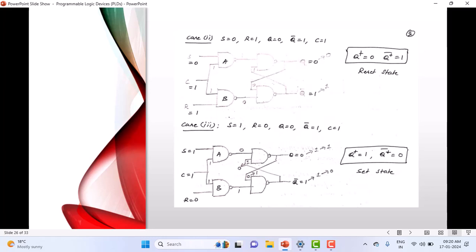And again 1 comes here, 1 is there already. So 1 and 1 remains as 0. And look here, the 0 goes over there, and 0 and 0 remains as 1. So that means the stable state is 1 and 0. Okay? Understood? Even if you analyze for half an hour or 1 hour, the state remains the same, 1 and 0. So what I can conclude now is, for this particular input, this assumption, clock is 1, the next state is going to be Q plus equal to 1, Q plus bar equal to 0. Understood this thing? Alright.